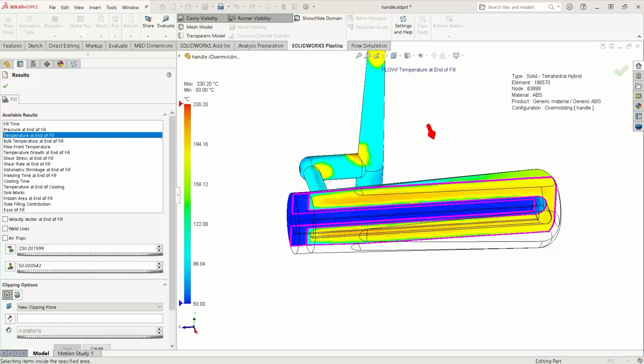In the flow direction, you'll have one set of properties, typically a lot stiffer compared to the cross flow, and that difference between the properties in the flow versus transverse tends to exacerbate when you have a higher percentage of glass fibers. So again, at 15%, the difference in the flow versus cross flow may not be as significant as at 35%. So these are things that you have to keep in mind.